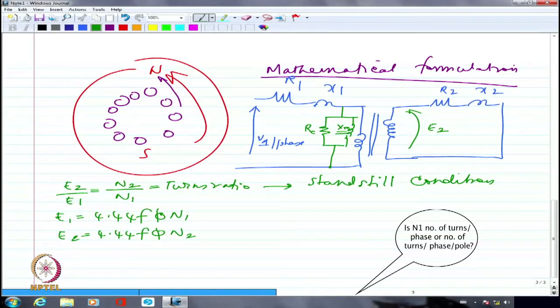Sometimes I may connect some of the windings in parallel or series, depending upon whether I want a high torque machine or high speed machine, high power machine. Depending upon my ratings, I might connect all the windings in series or parallel, similar to lap and wave, what we talked about in the case of DC machine.